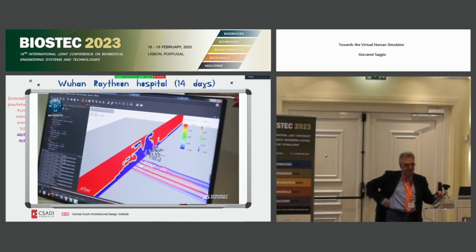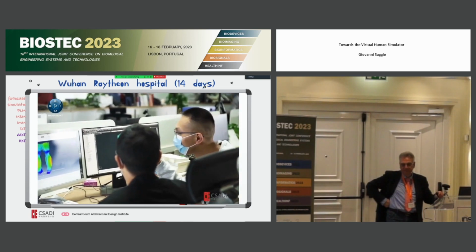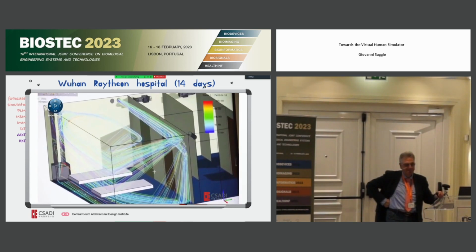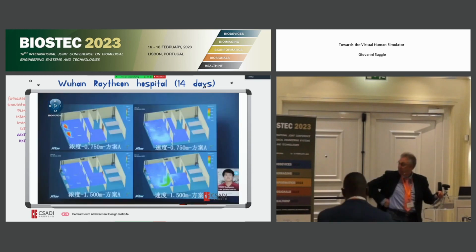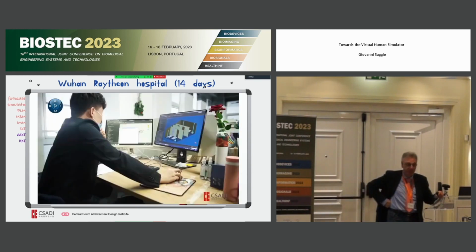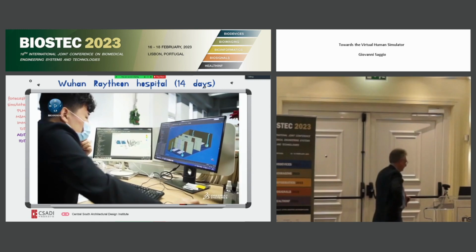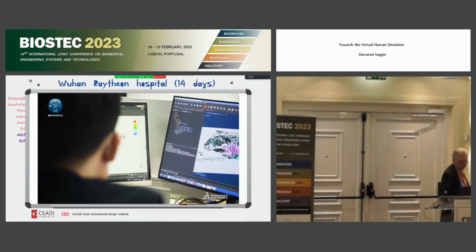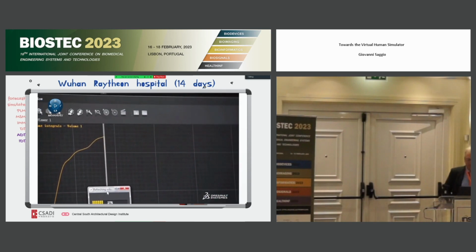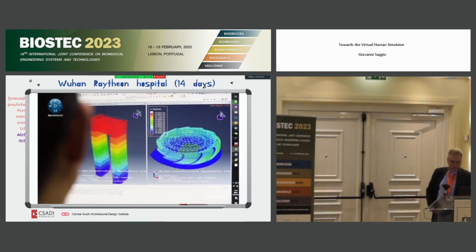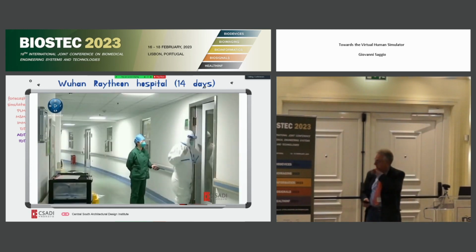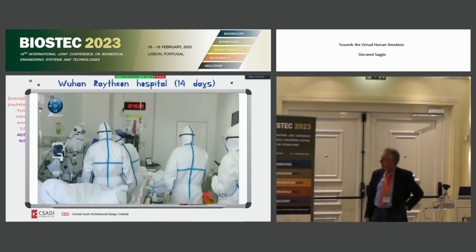to simulate the indoor airflow of the patient rooms and wards in Leishenshan Hospital to see how COVID-19 would spread. We also used X-Flow to simulate the impact of diffusion between patients and medical staff, the pollutant density, and the HVAC layout. We developed the optimal design based on these results and gave recommendations on how to control the indoor pollutants in the patient rooms and in hospital wards, and how to build a similar hospital later on.